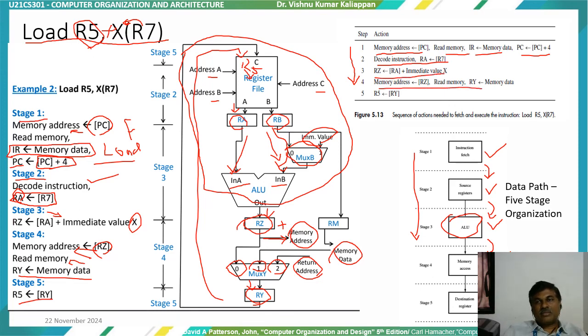After the arithmetic operation, move to the memory based on the instruction. As per here, we are moving our answer to R5. So this is a very simple way of understanding how the register file, ALU, and memory are correlated to execute the given instruction with respect to these 5 stages.